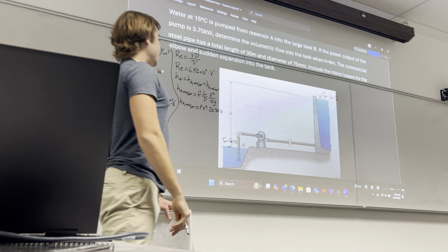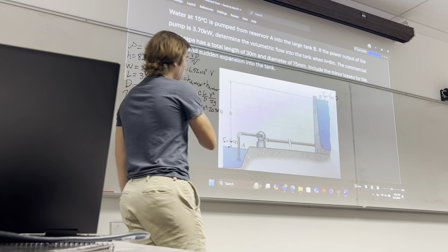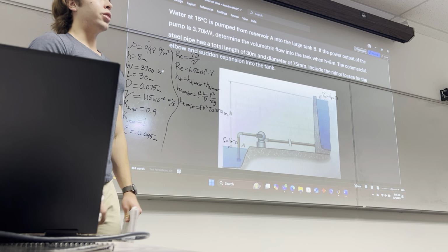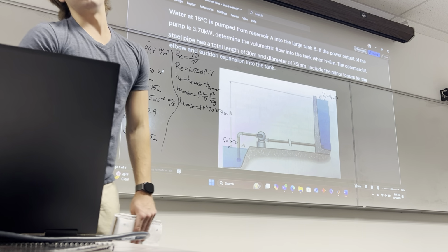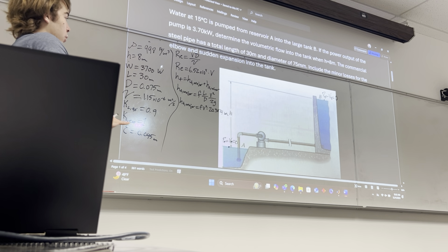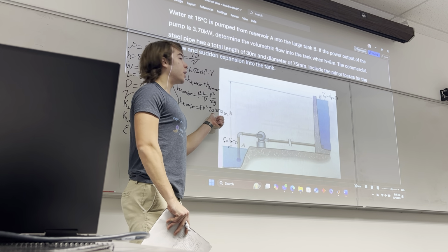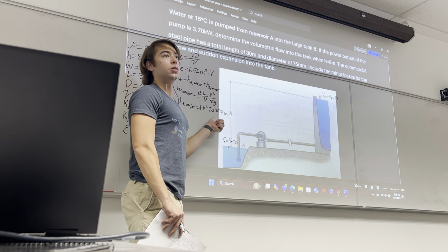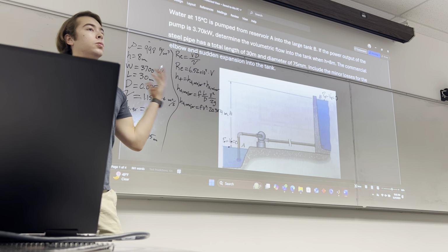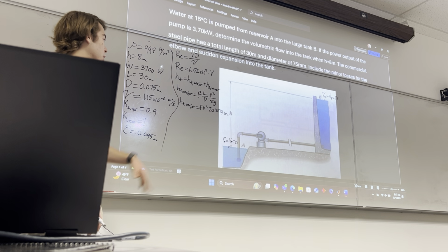And important to note, the losses in the scope of this form will be in whatever length scale unit you're talking about. In this case, it's meters, okay? The way I think about this physically, and I don't know if it's necessarily the right way to think about it, is that when I read that number, I think, due to the major friction losses in this pipe, I'm losing like 20 meters of available pumping distance. I don't know if that's actually what's happening, but that's just how I quantify what's being lost. Okay, so we've got that part.